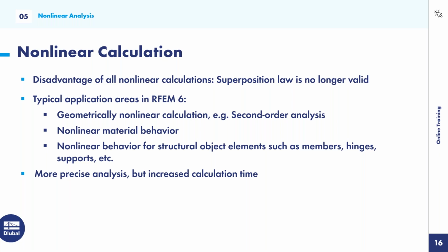And so you might have done some yield strength tests in your class or in a lab with a steel sample, and you can see how the stress strain graph is normally linear with respect to stress and strain, and this can become nonlinear when it enters the plastic region. And so this is an example of where nonlinear materials would be considered, and there's also some examples of nonlinear materials like glass, silicone, and cable elements where their stiffness changes depending on the forces applied to them.